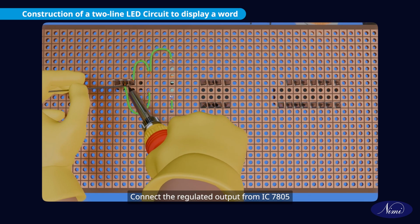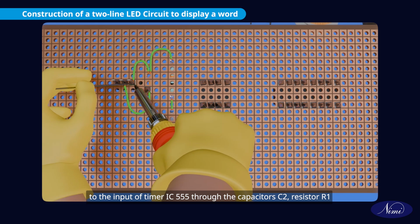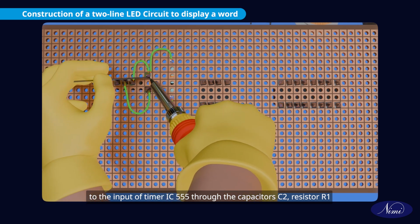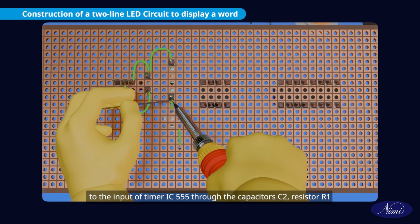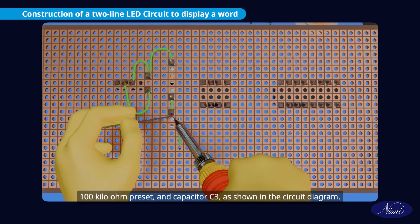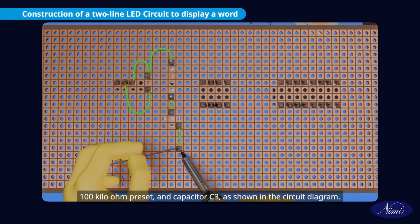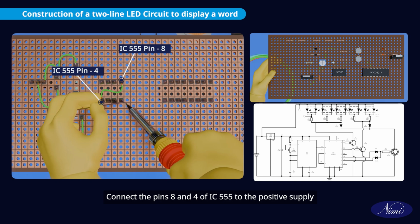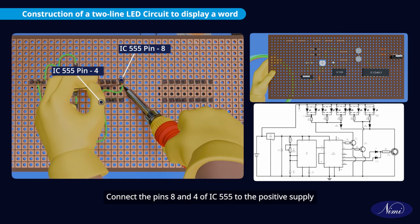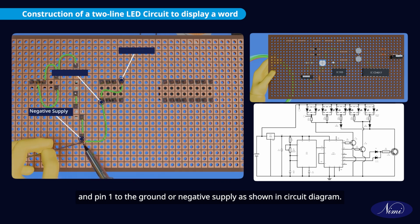Connect the regulated output from IC 7805 to the input of timer IC 555 through the capacitor C2, resistor R1, 100 kilo ohm preset and capacitor C3 as shown in the circuit diagram. Connect pins 8 and 4 of IC 555 to the positive supply and pin 1 to the ground or negative supply as shown in circuit diagram.